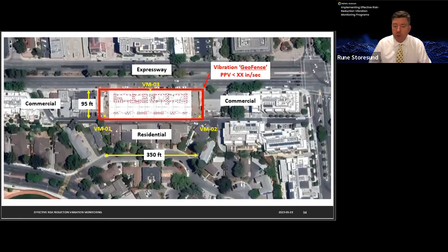Next, a geofence was established around the construction perimeter for which alarms would be disseminated should the project threshold PPV values be exceeded. This part of the enhanced reporting was not functional during the actual data collection period, but we're using it for development purposes as we configure the enhanced reporting features.